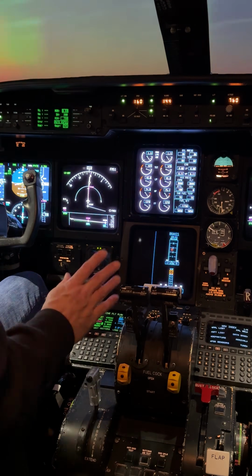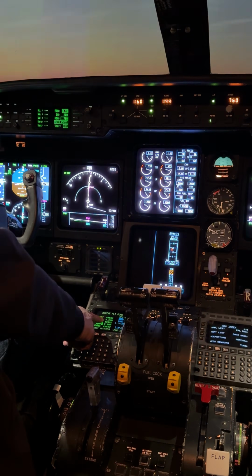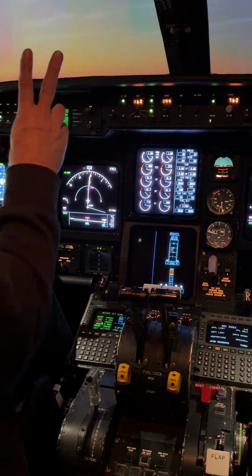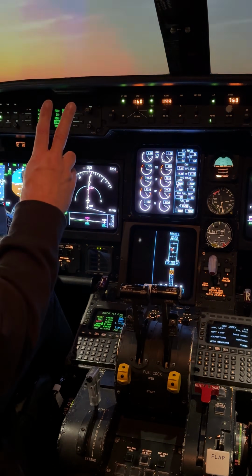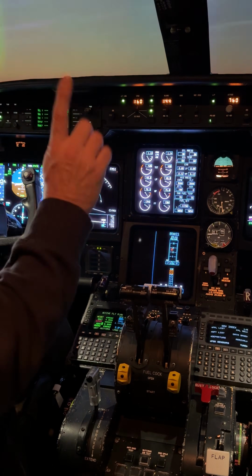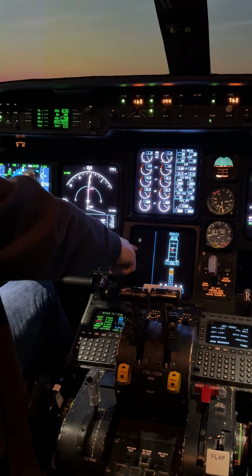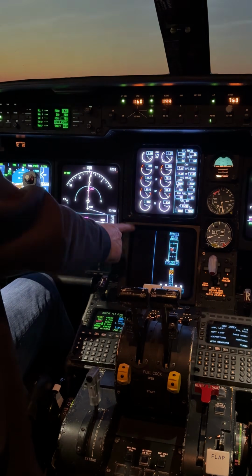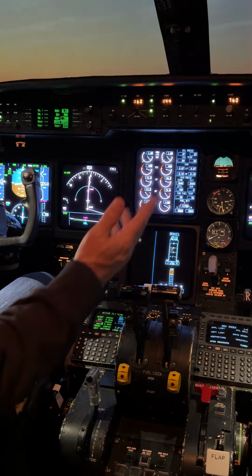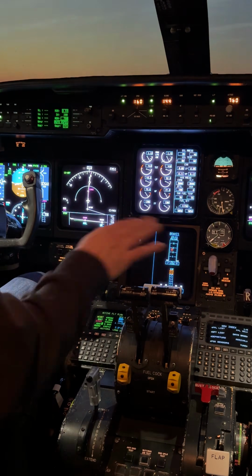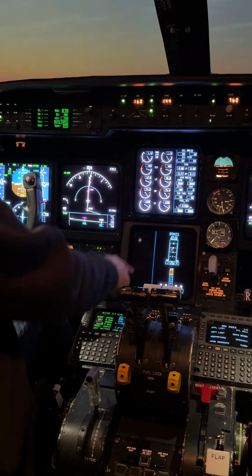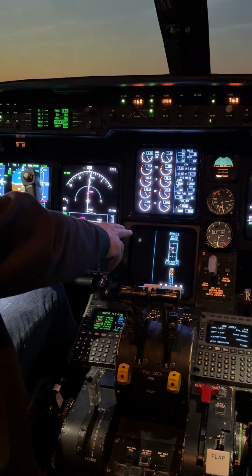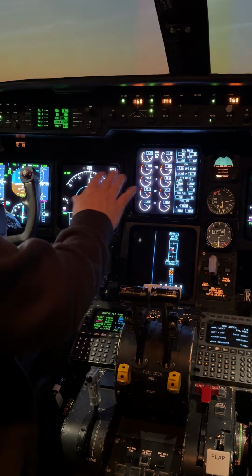All right, something else that's going to happen. We're about 4.5 miles away from Ginny. That's the final approach fix. When we get to be 2 nautical miles from the final approach fix, we are going to see, and better see, 2 lights up here. It's going to say FMS1 approach, FMS2 approach. You want to make sure that you have those 2 lights. There's actually 4. There's 2 here, 1 on each FMS for a total of 4. So you're going to have 2 here, 1 here, and 1 here for a total of 4 lights. If you don't see those 2 lights, it's a missed approach, and you come back and do a different type of approach.